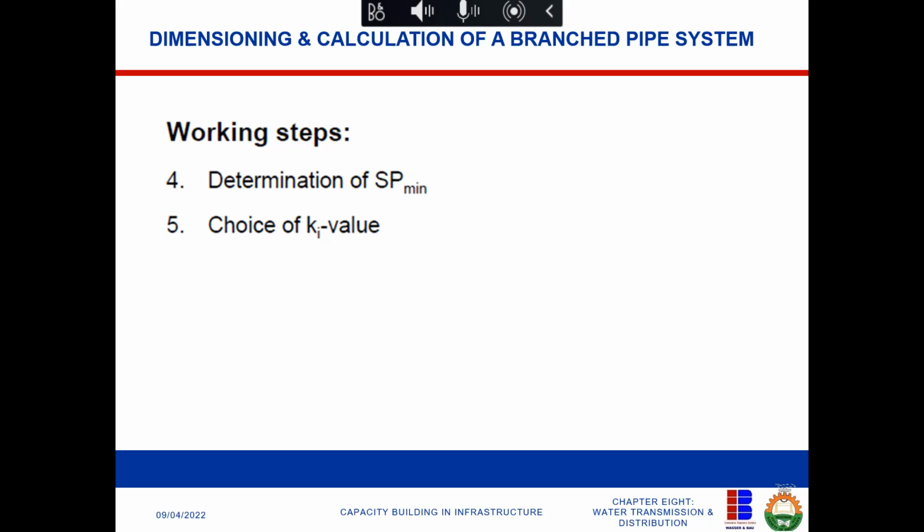So it means that 6 meters becomes your minimum service pressure. It means anything you are adding height, you're already adding 6 meters. If you are building an elevator tank, you're already adding 6 meters to anything you want to build, because the highest building is already on 6 meters. But as you know, we do it in terms of meters.